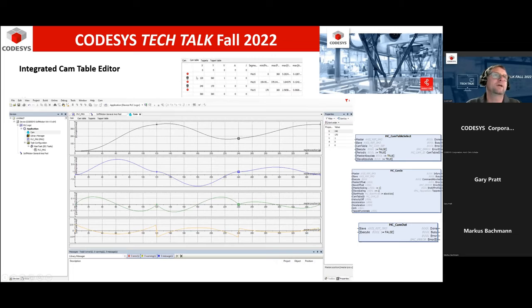When our master axis is at 120, we're going to be at 360 degrees. So that means once it's coupled in, once you send this cam table right here down into the controller and you say cam in, at that time, once you start, you do a velocity start, and you're doing a modulo rotary. You're spinning it in a circle.